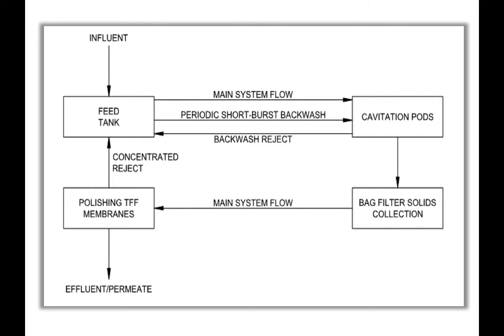There is a backwash of the cavitation pods themselves, and it's very quick, it lasts about a second, and it happens very often, every few seconds. So they just kick water back into the cav pods, and then the water kicks right back into the feed tank with any solids that are starting to build up on their screen or their process where they're inducing that cavitation.